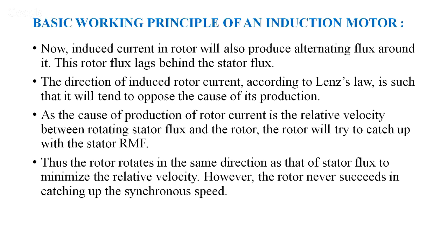There is a relative velocity difference between the two fluxes, and always the rotor flux tries to catch up with the stator flux. Thus, the rotor rotates in the same direction as that of the stator flux to minimize the relative velocity.